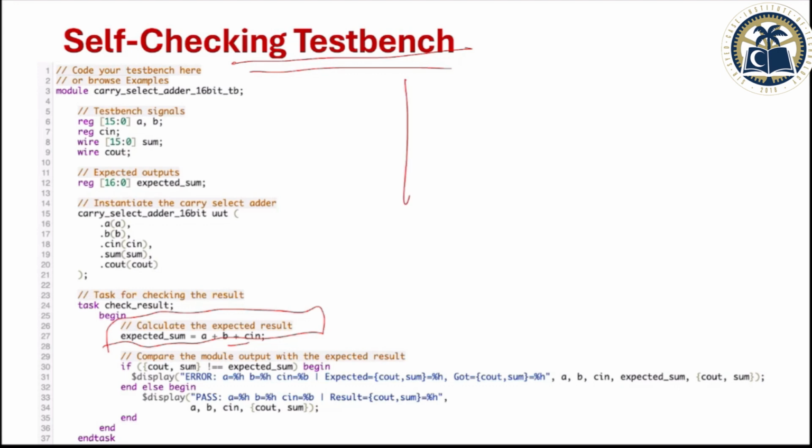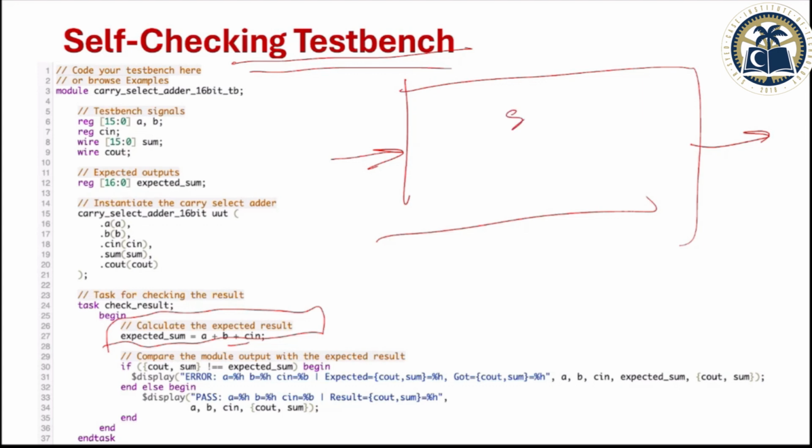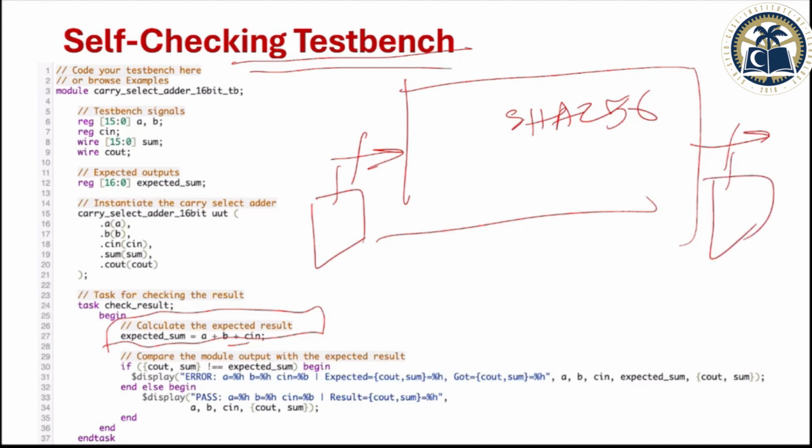So you have a Python implementation, you take the test vectors, generate all the outputs, then give the same test vectors, and one by one, either you read the answers from a file. If you are doing white box testing, it becomes even more intricate, because one is black box. Black box is you give input, you get an output, like we are studying SHA 256, okay? You give a lot of inputs, generate a lot of outputs, put this in a file, and then read both files in your stimulus and start generating.